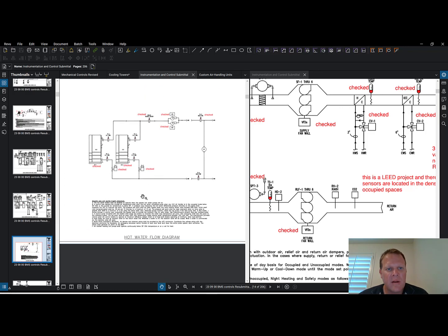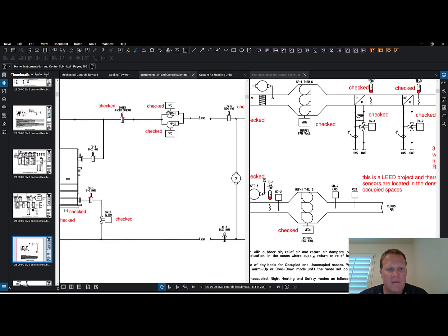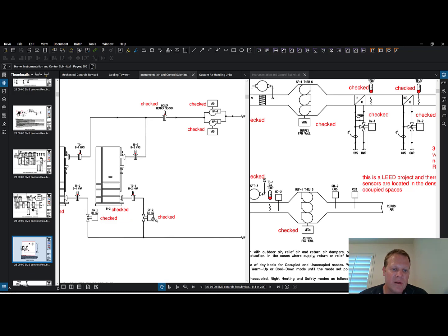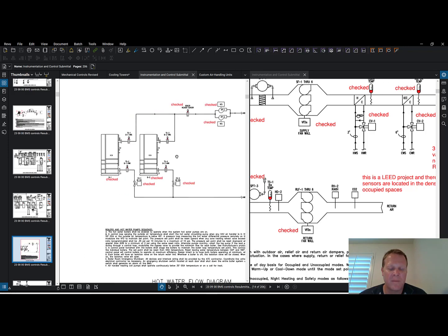It doesn't matter. I'm hoping you just saw, what do we have here? We have some hot water pumps run by VFDs. What's that? That's a sensor. What's that doing? That information is being sent back to the controller. How effective was our hot water? Hey, are we doing okay? Anyway, there's a valve right here, a check valve, probably a motorized one. Why? Because they're deciding whether to let this water go in here or not and get warmed. I'm sure there's a ton of controls for this as well that we're not looking at.